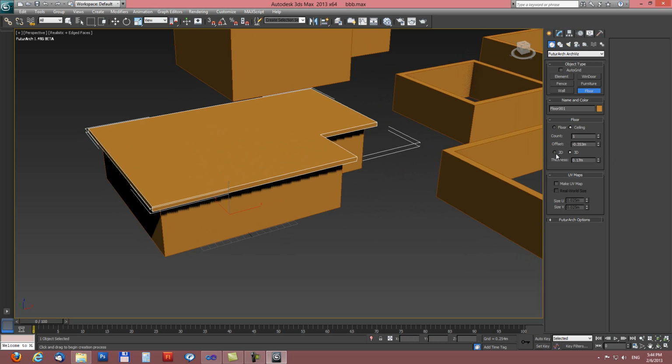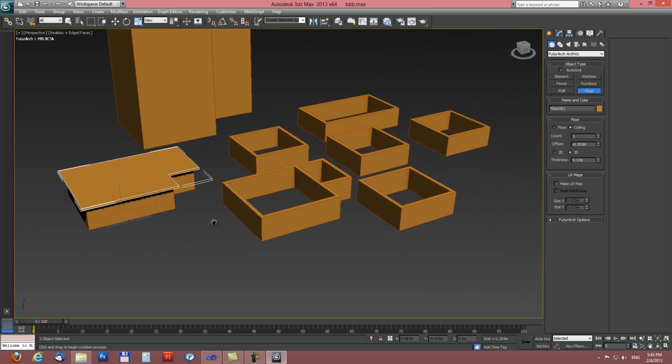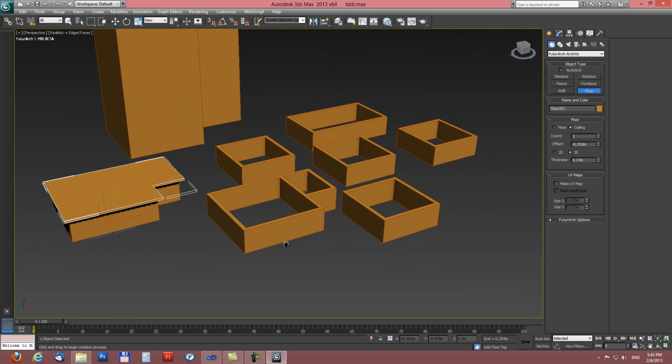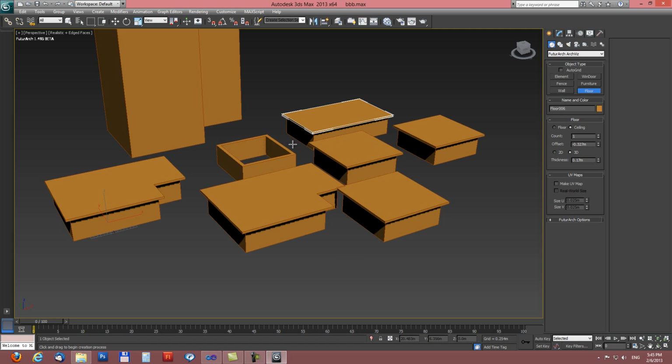We can set also 2D mode. In 2D mode there is only one flat polygon. In 3D mode we can control also thickness. With the right mouse button or the S key we end the tool, and we can apply this tool very quickly to another wall object, just by clicking the mouse button on the appropriate wall.